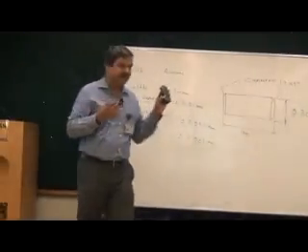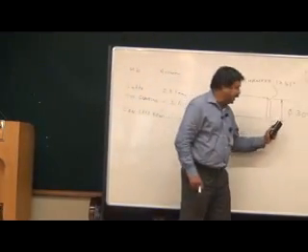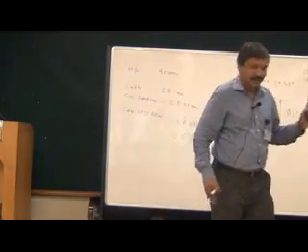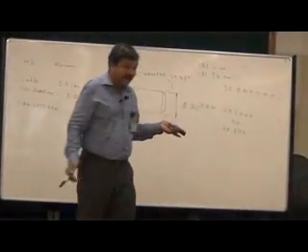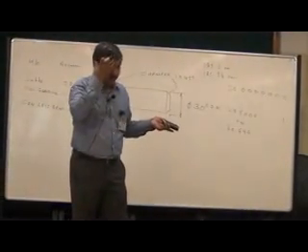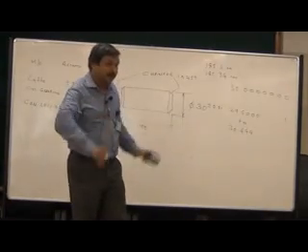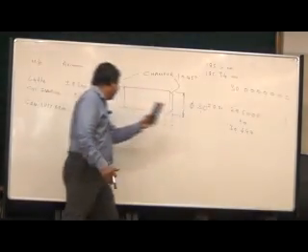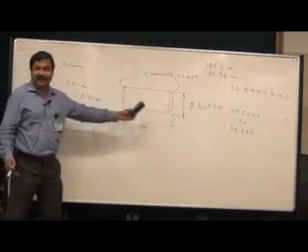The shaft will be accepted if the diameter is anywhere between 29.99 and 30.01. The diameter must lie within this range. Then he can choose an appropriate manufacturing process to realize the diameter.